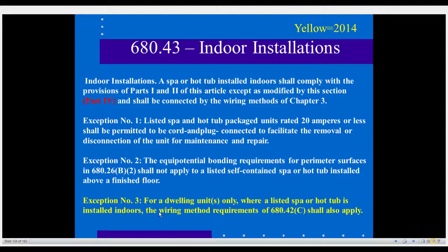In other words, I'll let you use a cable, like a non-metallic sheath or an SE cable, a wiring method, for example, that has an enclosed outer sheath with an equipment ground in there that is not insulated, like an SE cable or type NM. I'll let you use that. If you want to run one of the raceway methods, then I'm going to want an insulated equipment ground. But if you put one within an outer sheathing, then I don't care. It just can be enclosed within the outer sheathing.